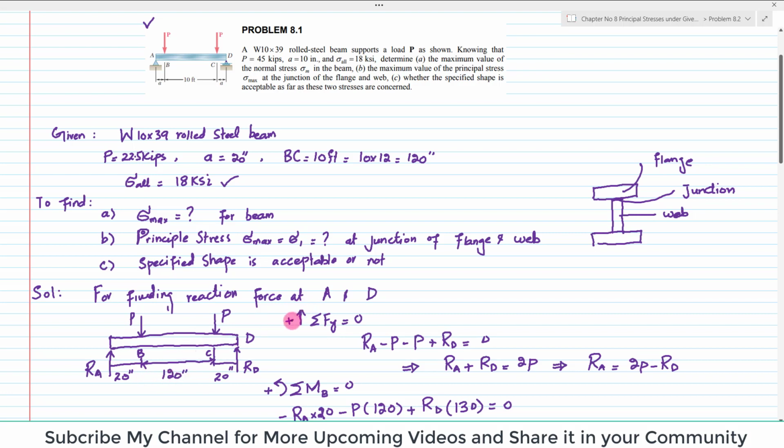Clear? By using the first equilibrium condition, that the sum of all forces along the y direction is equal to 0, you can see RA is upward, so RA minus P minus P plus RD is equal to 0. So RA plus RD will be equal to 2P, or we can write RA in terms of P and RD, which is this one: RA is equal to 2P minus RD. So this is the first equation.